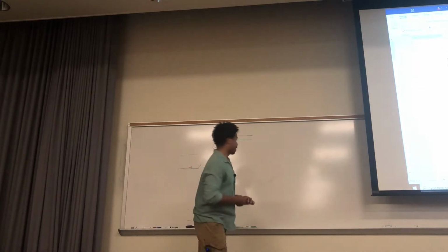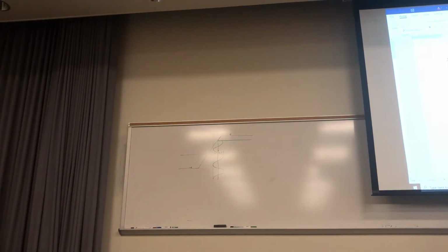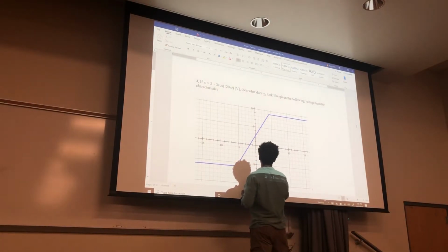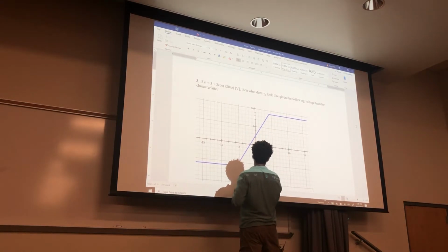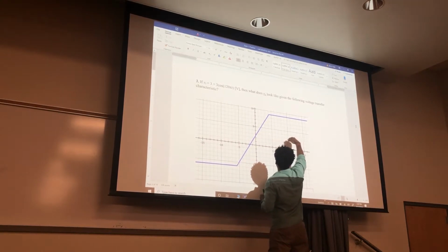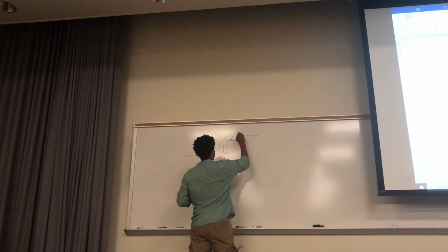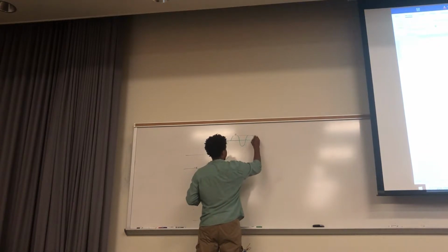And then what's going to happen is that, so that's at 3, 1, 2, 3, so it's going to be right here. You can clearly see that that's going to be some clipping. This center one is going to go straight through like that. And this one's going to come up to around here and then go over. So the bottom's not going to be clipped, but the top's going to be clipped. So it'll look something like this as it comes out, where it's clipped, clipped, sort of like that.